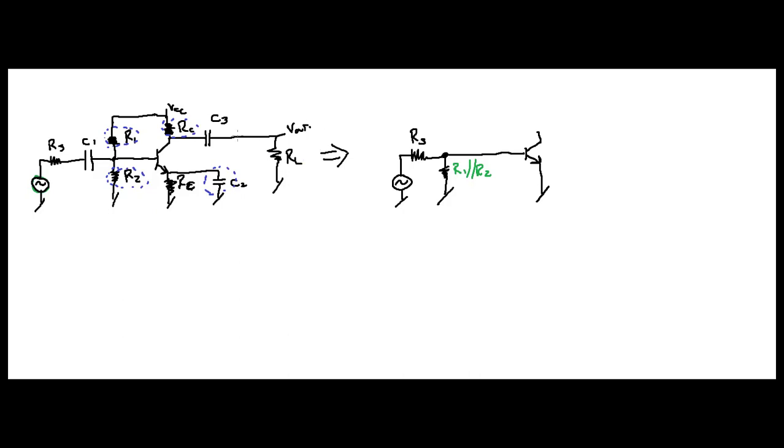And your capacitor here looks like a short. So these two can be combined, and they can be thought of as a resistor in parallel. So you draw that one, in green too for you. This is going to be RC in parallel with what? RL, right?